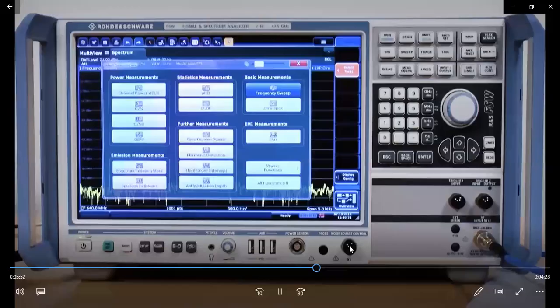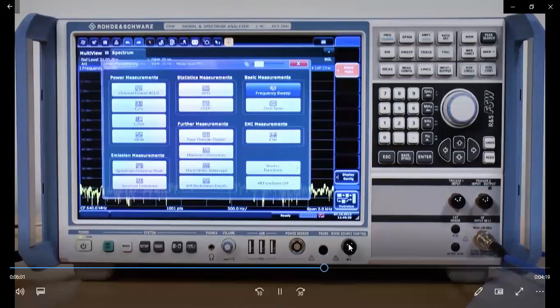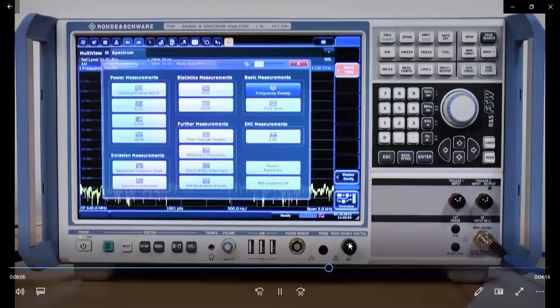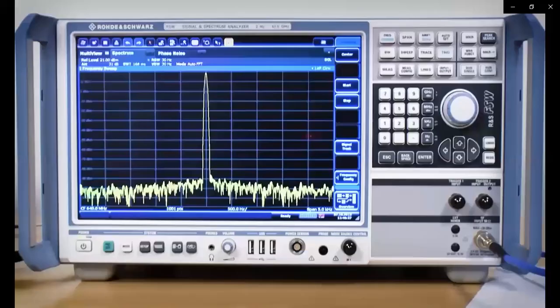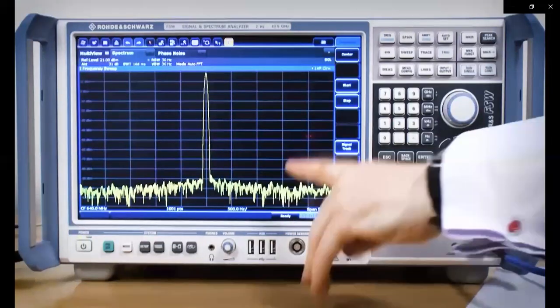With spectrum analyzers relying heavily these days on processing technology, they often contain many inbuilt routines. These cover many functions, everything from channel power to harmonic distortion, and third-order intercept to AM modulation measurements. Two routines that deserve special mention are phase noise and spectral emission masks. Phase noise is a critical parameter of many oscillators and systems. High levels of this noise can cause many issues. Unfortunately, all signals have some level of phase noise on them, as can be seen here.